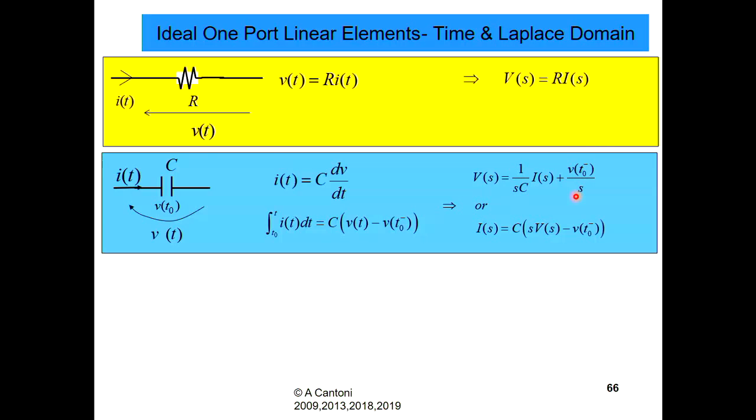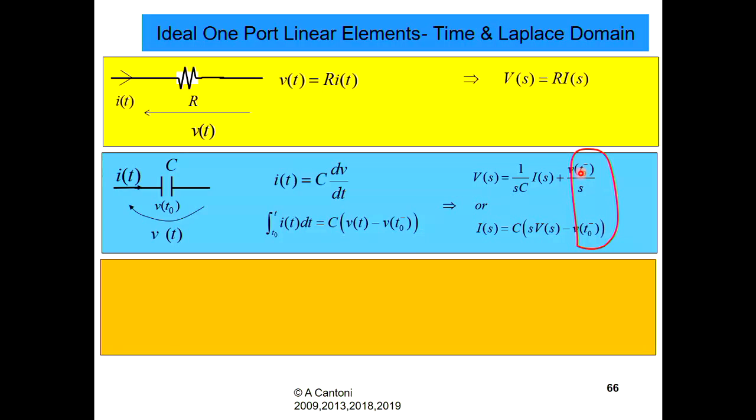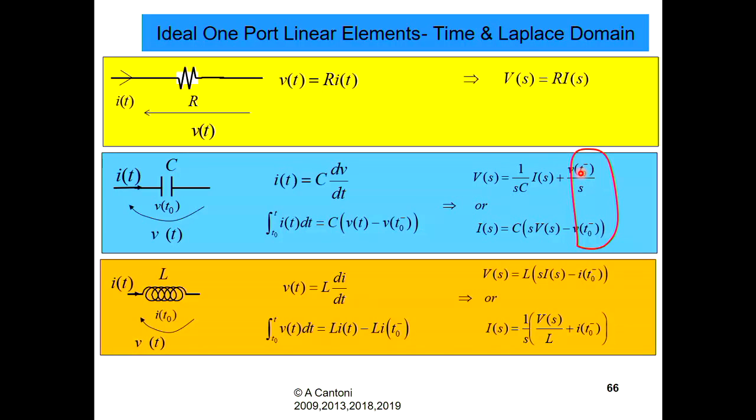So also a voltage source in this particular case, or a current source. They come from the initial conditions, which come from here. So that's what you can do in the Laplace domain. You can't do that in the frequency domain, but in the Laplace domain you can include initial conditions. The inductor, again, in the time domain is just a simple differential equation. The integral form captures the initial conditions, but in the Laplace domain we always have the initial conditions there.